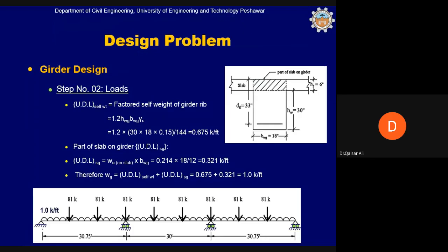Because if you look at the beam, the analysis is being done based on the clear lengths, so the point load is coming from the clear length, and clear length does not include this slab part. Okay, you think on this, and if it is not clear, you can come up with a question on this next time. This will need a little bit of thinking, so discuss it among yourselves. If it is not clear, then you can discuss it with me.